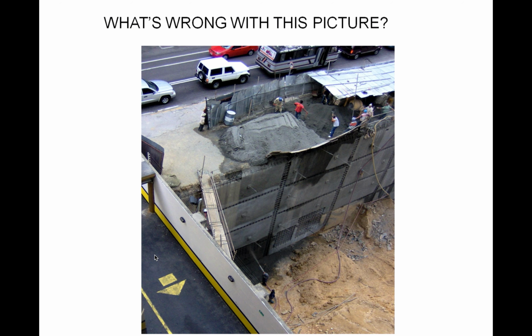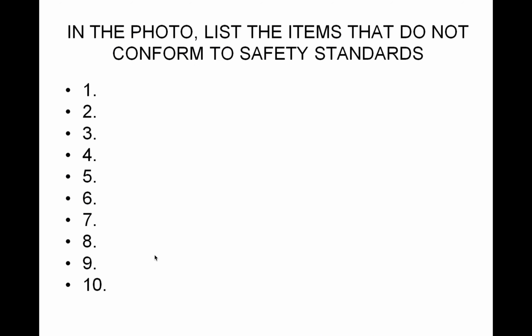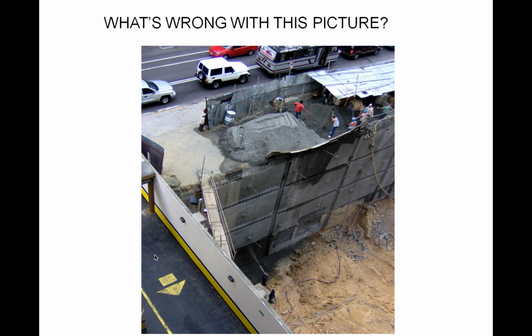As you can see, folks are not wearing proper equipment up top. Many people don't have hard hats. There's no safety vests. You can see a guy wearing sneakers. This is not something that should take place, and it would not be allowed here in the States. So basically, I just went through that list. There's a couple more things. The entryway is not clearly marked for vehicles for deliveries. It's just all kinds of stuff.